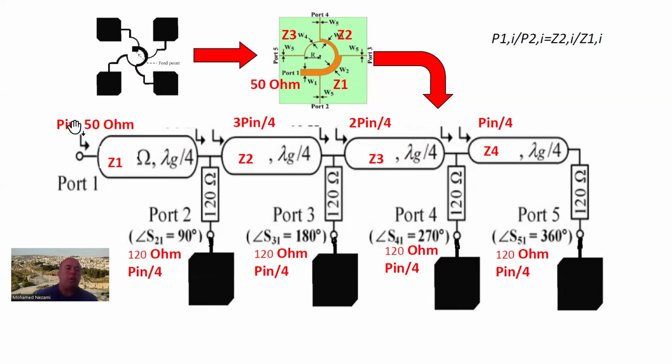So we come in here, we have 50 ohm known in here. Let's look at the first junction. We're splitting so that 1/4 of the power goes in here, but 3/4 goes here. Why 3/4? Because we have 3 elements to deliver power to. So 3/4 of the power has to go this way. So we know that this T-junction splitter splits the power 1/4 to 3/4.